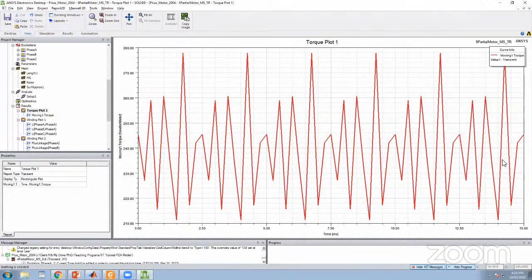Remember, it is claimed in the report that this motor can generate 400 Newton meter, right? A peak torque of 400 Newton meter. That is when we overload the machine. We give it a current that is much, much higher than its continuous rating current. So we can use this motor to generate 400 Newton meter if we increase the current. But when you overload the machine, it can only operate in that situation for a very short period. For the Prius motor, that is 20 seconds.